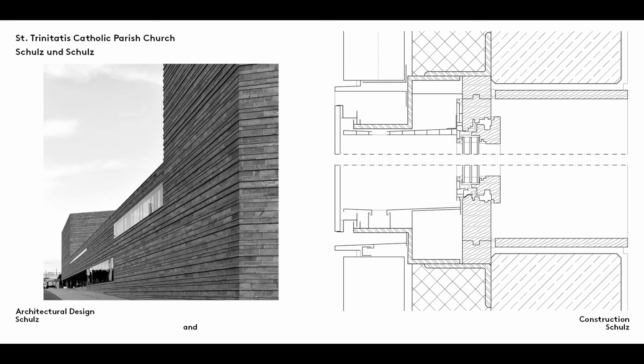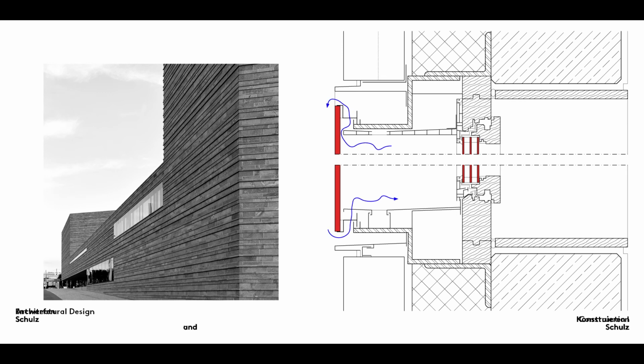Before the invention of double glazing, box-type windows were used to improve thermal insulation. They consist of two panes of glass positioned some 10 to 20 centimeters apart and can still be found in some historical buildings. Today, box-type windows are constructed with an inner double or triple glazed window and an outer single pane to form a cavity, which is then ventilated.